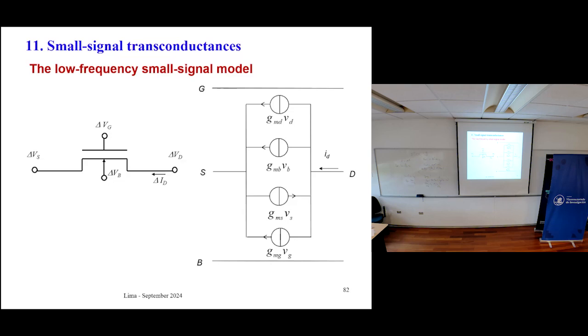So in general, we use long channel models to calculate the DC current. But of course, you cannot do it for calculation of a voltage gain, because you need the slope of the characteristic of ID versus VD. So you need some, I would say, experience to deal with each problem. So you have to get some feeling about the problem that you have to solve. Okay? Any other question? No?